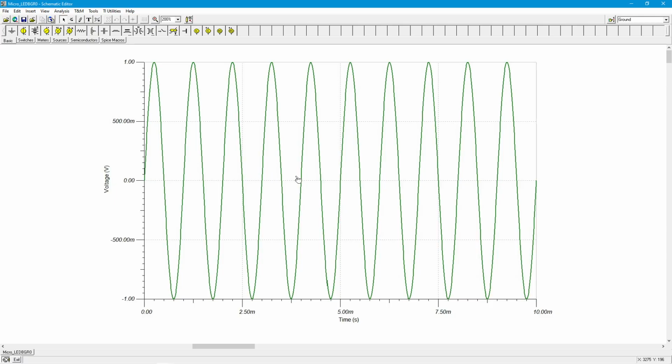So, it's a 1 kilohertz waveform. Okay, I just happen to have my ISR every millisecond. So whenever it hits this point, boom, that's what I take my measurement. It's not going to be accurate. I need a way of sort of stretching this out, some way of improving my odds, if you will.